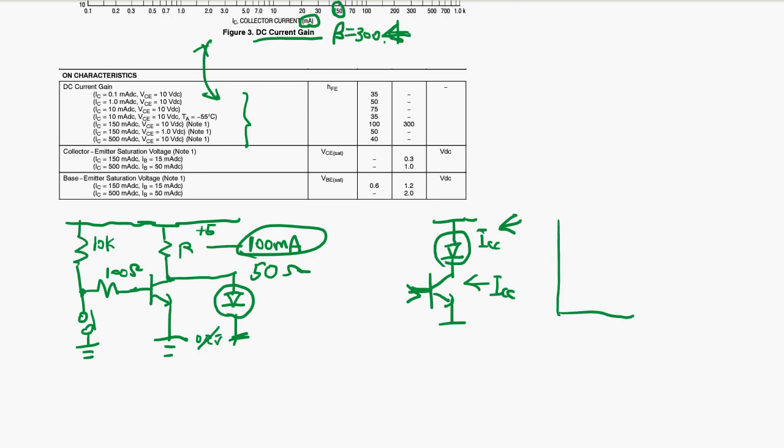Then on the PC board you have LED lamps where this is bright, this is dark, this kind of thing happens. But if you use the resistor and current flows this way, then the resistor is pretty much consistent in every circuit, plus or minus 10% worst case. So with this configuration LED brightness is going to be consistent, so we use this configuration.